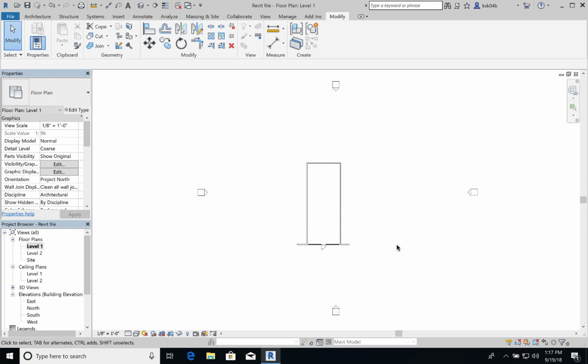In this video, I'm going to show you how to create your own custom sheet in Revit. So the standard full-size sheet for architectural drawings is 24 by 36. The reason that is the most popular is because when printed at 50% scale, it comes out to an 11 by 17, which most people with office settings can print in their office and then know that since it is half size, all of the drawings will be half scale.